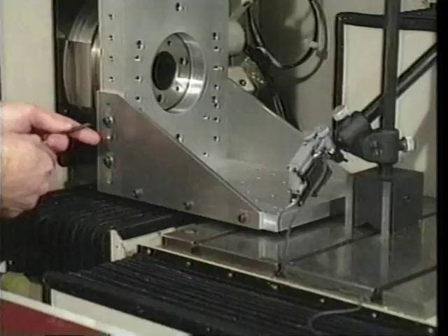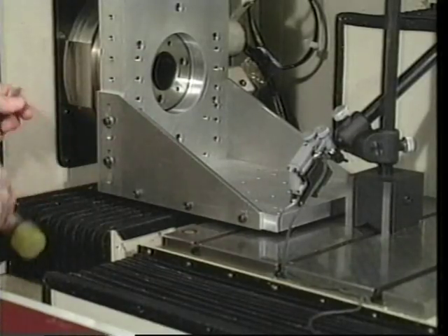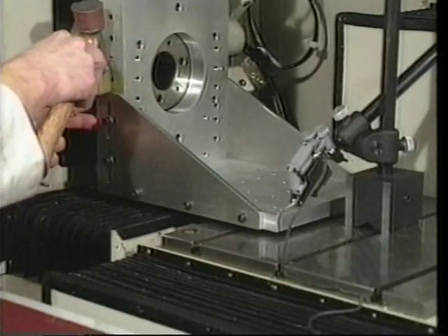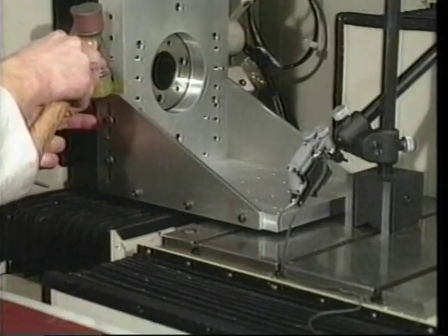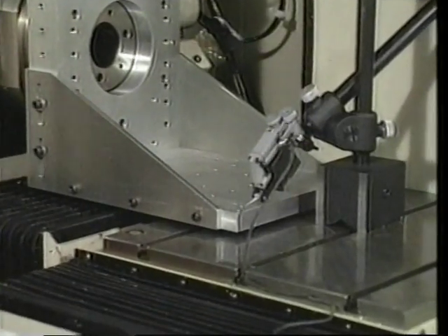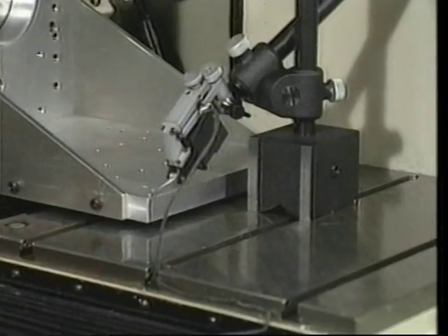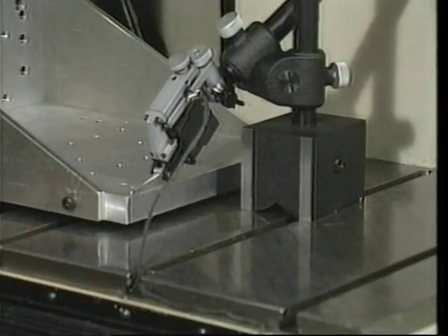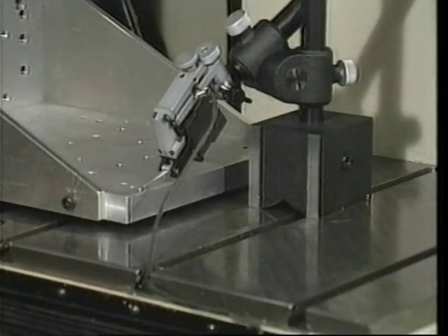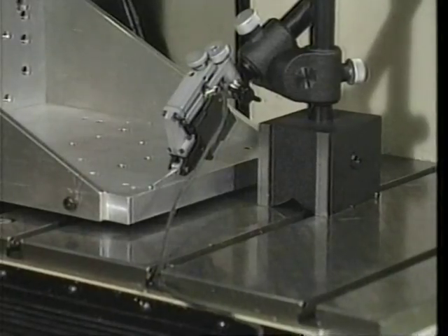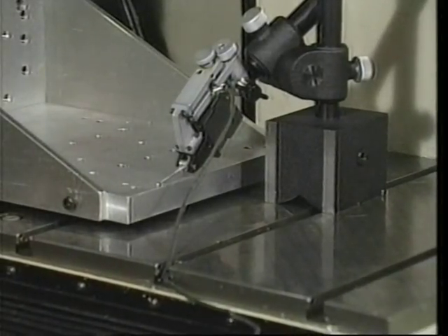Efforts are also made to horizontally align the platform with the x and z axes. This is done in an attempt to keep the probe orthogonal to the straight edge during both steps of the measurement, as well as to minimize path differences along the straight edge between steps 1 and 2. The averaging nature of the capacitance gauge also reduces the effects of path differences.